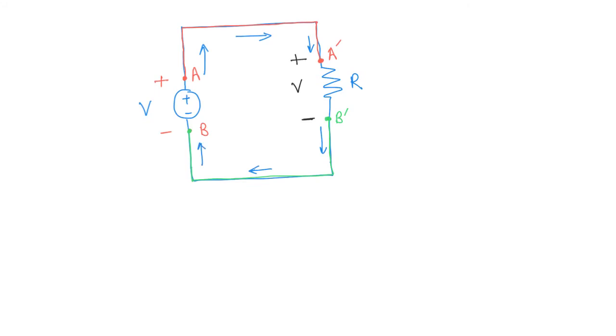Now, one of the things that you should remember in all electronic circuits is that current flows in closed loops. What that means is that if a current is going out of this voltage source, the same current has to return back to it. And the reason that is true is because we cannot have any accumulation of charge in this circuit. Neither can we create or destroy charge. So the current that is going here needs to return back.